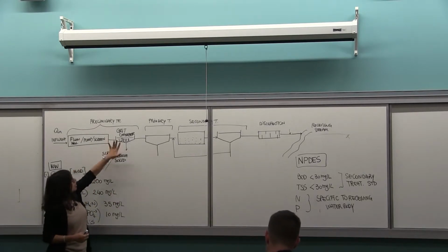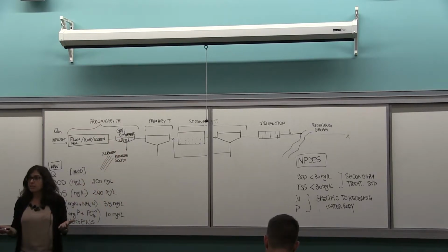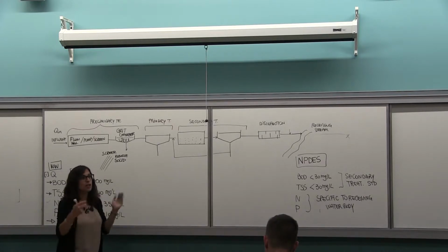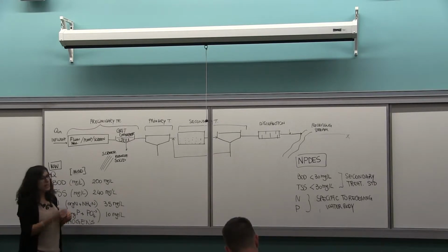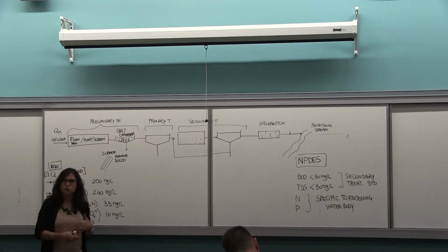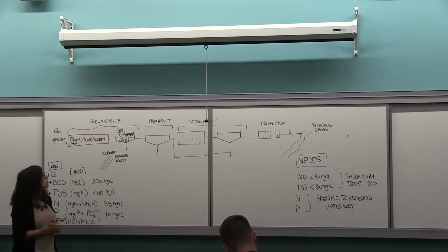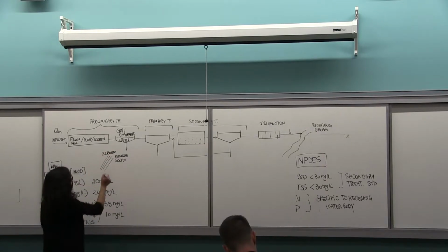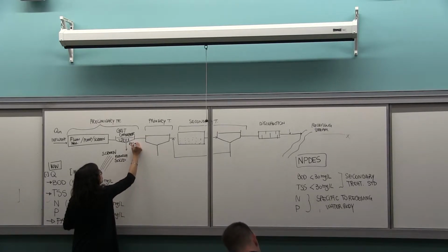We're not doing a problem on the grit chamber, but the design is very simple. Usually the residence time is 2-3 minutes. You have your flow, and you can determine the size of the tank based on that residence time. The airflow is usually part of the design as well. There is a range, how many cubic meters of air per cubic meter of flow that you are treating, so a very simple calculation. So the screen removes solids, and the grit chamber removes sand and grit.